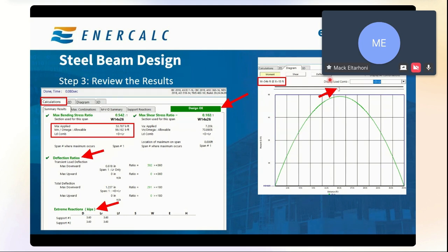Same thing for shear, or if you have specific deflection. So you can use just the slider, and in this case, at 15, you're getting the maximum moment, which makes sense. But you can slide it left to right to see what kind of information you desire at a specific location. So very simple, very intuitive, straightforward and easy module to use.